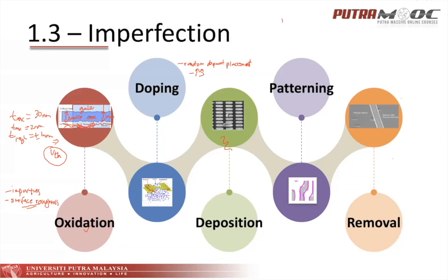So this is the reason why during the manufacturing process, we can observe parameter variation in the transistor parameters. So when we go to smaller devices, it is important to control the position of the dopant so that we will have a consistent transistor performance. So for example, we really want to have a threshold voltage of 0.2 volt.